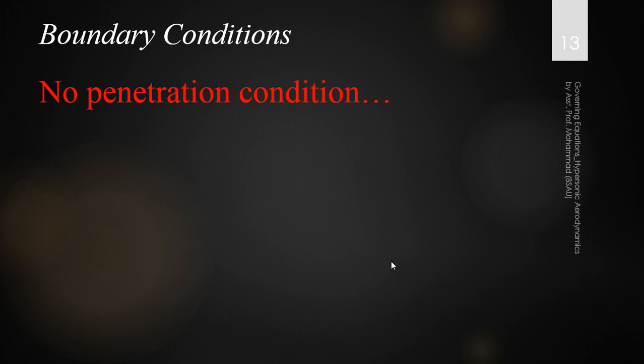The reason is this, we are dealing with inviscid flow right now. So viscosity is 0. Viscosity is 0 means there will be no boundary layer and no shear stress available on the surface. But still we cannot expect the fluid to enter into the surface of the solid. So there will be no penetration. It means when the flow reaches the solid boundary, its velocity will be tangential to the solid surface. It can only glide, it cannot enter into this.